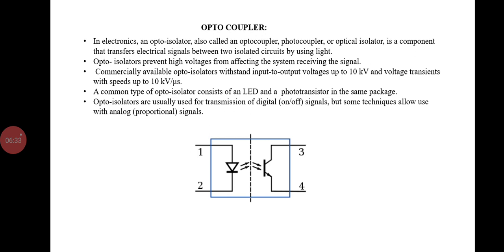An opto-isolator contains a source of light, almost always a near-infrared LED that converts the electrical input signal into light, a closed optical channel, and a photosensor which detects incoming light and either generates electrical energy directly or modulates electrical current flowing from an external power supply.